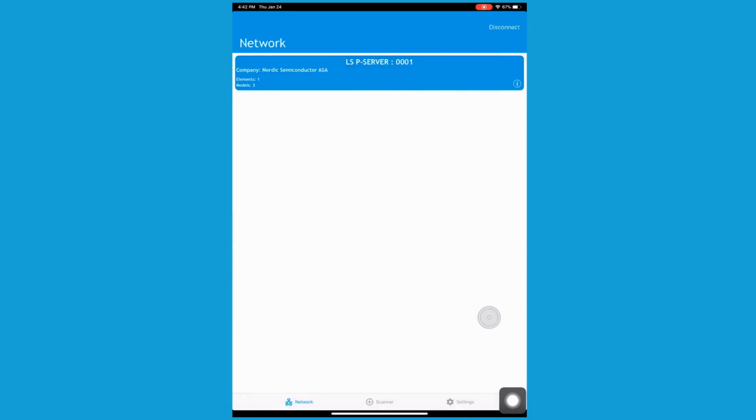screen. On the UW Terminal X screen, the mesh state provisioned adder1 count1 message confirms that the address of the first node is 1 and there is 1 element. The network screen displays all the nodes in this network. For now, there should only be one, LSP server 0001, where 0001 is the node address allocated to it.